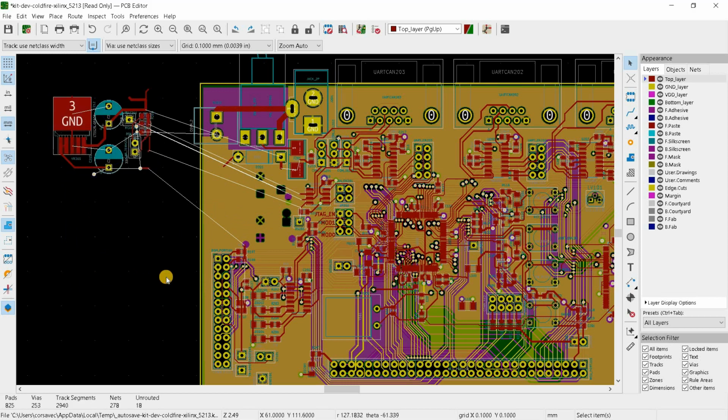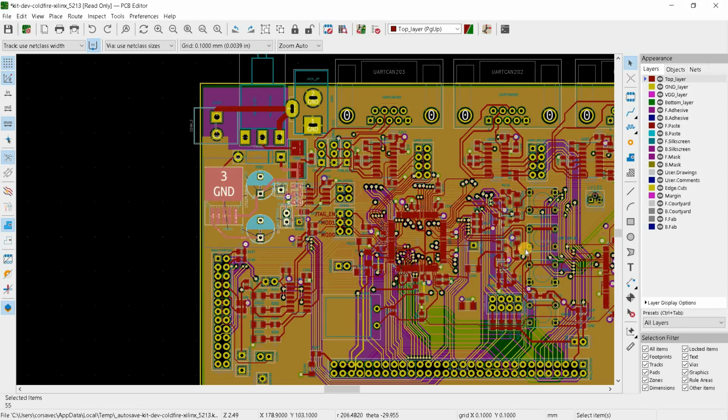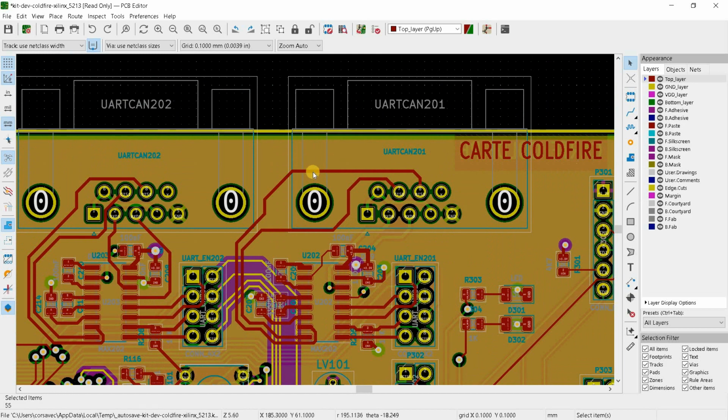What unpleasantly surprised me in KiCad 6 was the inability to quickly delete a track along its entire length. In previous versions, I hovered over a track, pressed the Del key, and the entire track was deleted. In KiCad 6, to delete an entire track, you must first select it. To select, click on one of the sections of the track and press the U key. The track is completely selected, and now I press the Del key to delete it.